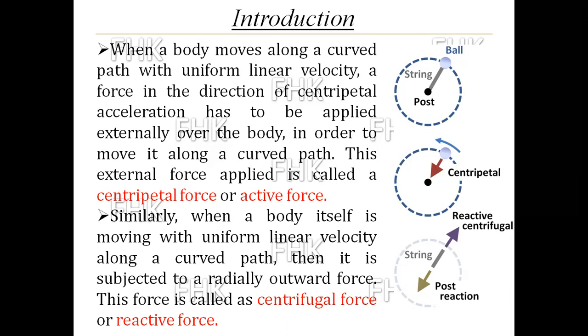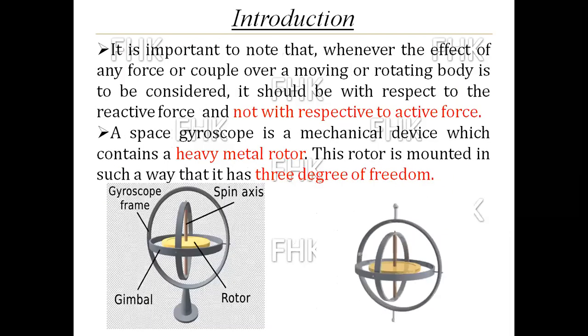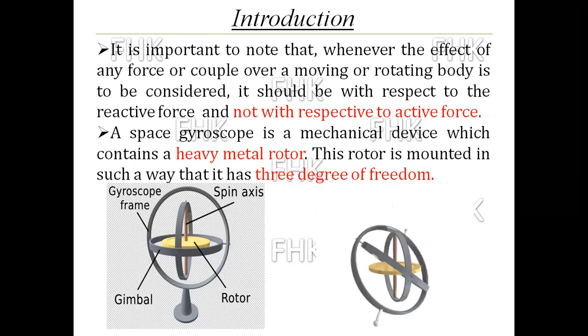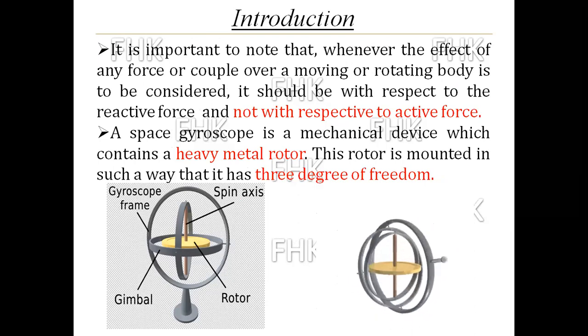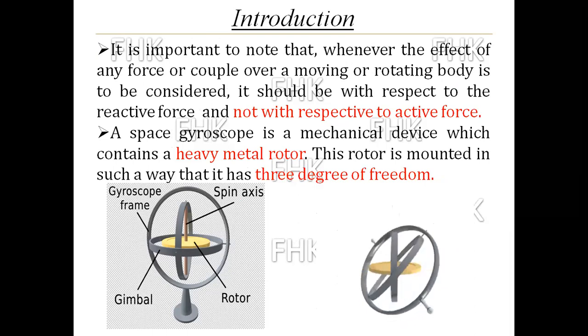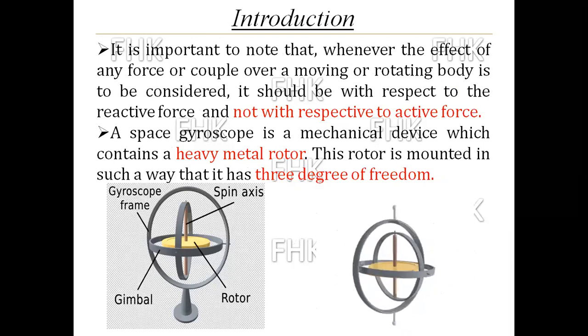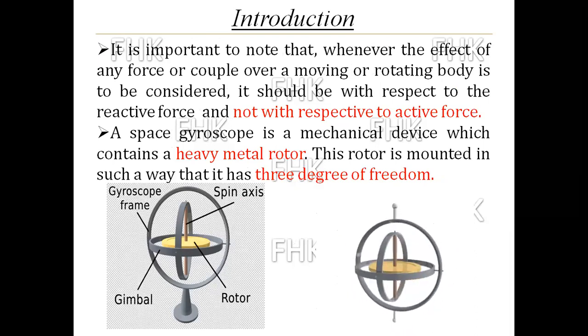Similarly, when a body itself is moving with uniform linear velocity along a curved path, then it is subjected to a radially outward force. This force is called a centrifugal force or reactive force. It is important to note that whenever the effect of any force or couple over a moving or rotating body is to be considered, it should be with respect to a reactive force and not with respect to active force.